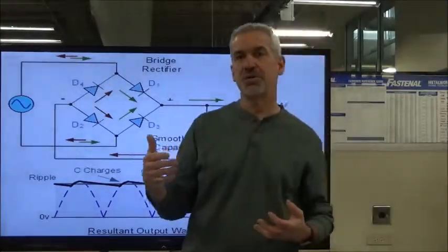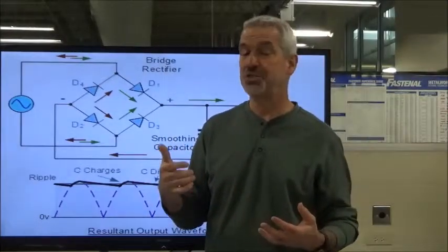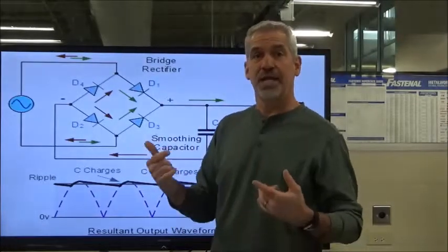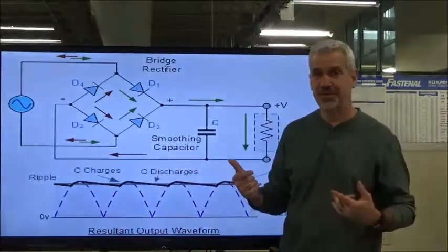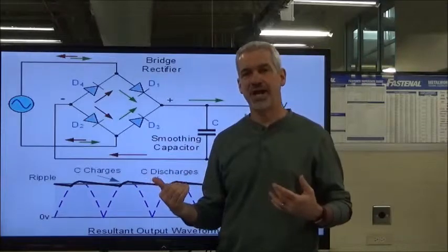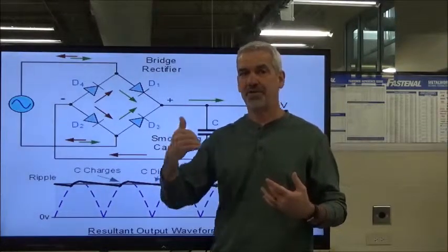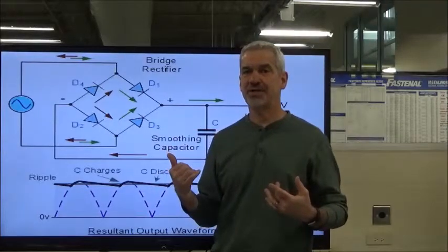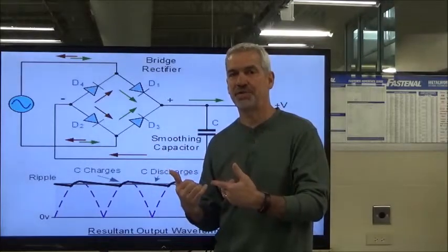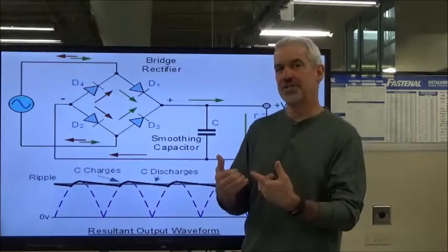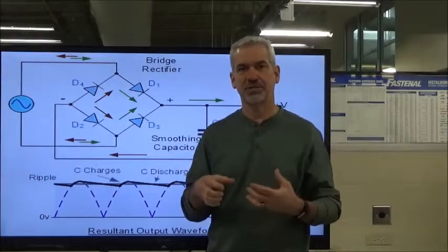It's taking the 120 volts and stepping down. How do I know this? Because you're not going to put 120 volts in an iPhone. You have to step that voltage down, and the iPhone has a battery in it. So we've got to rectify that AC voltage that we just stepped down from 120 volts. We've got to rectify that into DC, and it's all done in that little charging head.